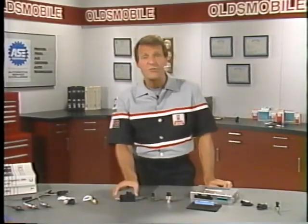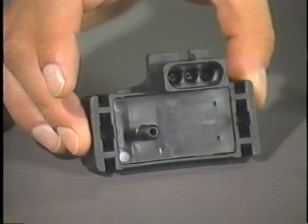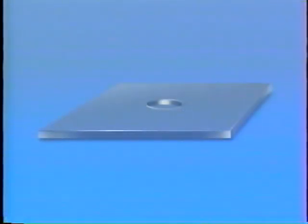The manifold absolute pressure, or MAP sensor, converts pressure readings into voltage signals. It does that using an electronic device called a strain gauge. A strain gauge is constructed using a very thin silicon chip and a small piece of glass with a cavity machined into its surface. The chip is placed over the cavity, and its edges are sealed so that it traps a bubble of air. That assembly is then put into a sealed housing, which is connected to manifold absolute pressure